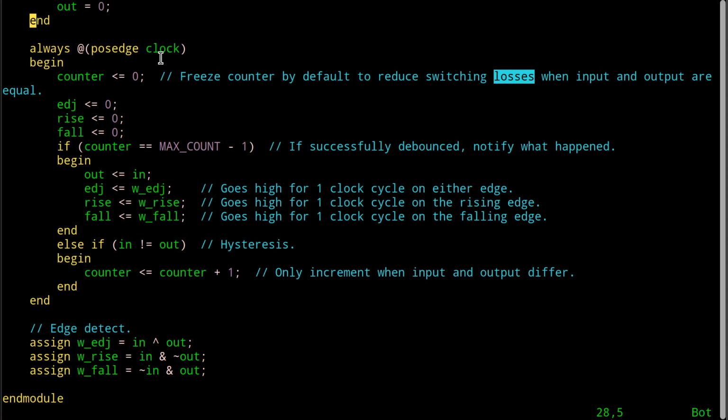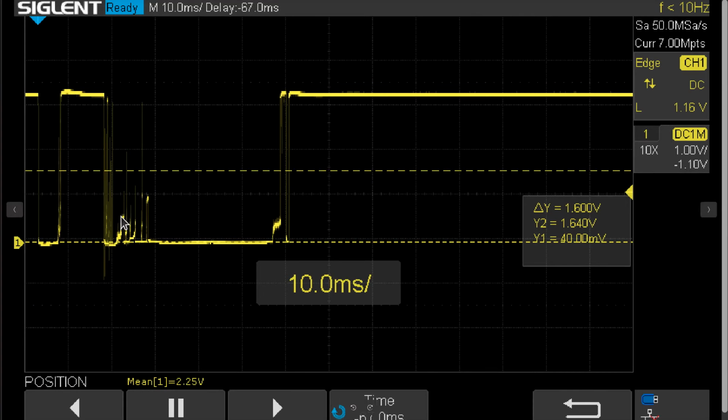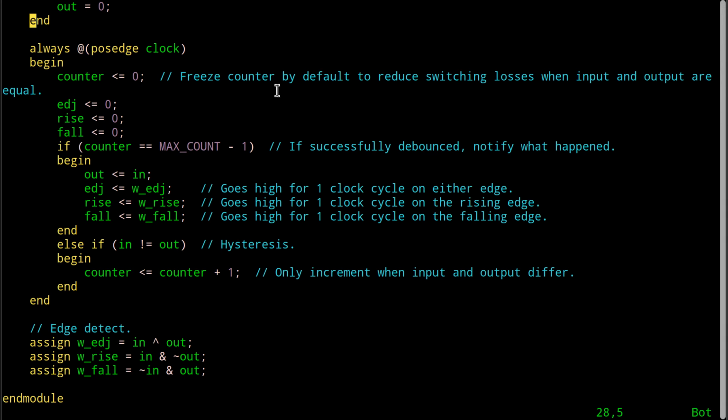The motive to do this, by the way, is we will see what he's going to do is, when I was talking about, let's start counting a delay when we see something change and say, if it stays changed long enough without it whipsawing back and forth like this, we'll just assume we're good and propagate that out at that time. What this note is referring to is, should this counter tick and advance and increase in value all the time on every clock edge or not?